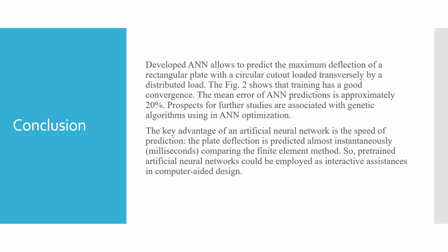So, developed NN allows to predict the maximum deflection of a rectangular plate with a circular cutout loaded transversely by a distributed load. Second picture shows that training has a good convergence. The mean error of ANN predictions is approximately 20%. Prospects for further studies are associated with genetic algorithms using in ANN optimization.